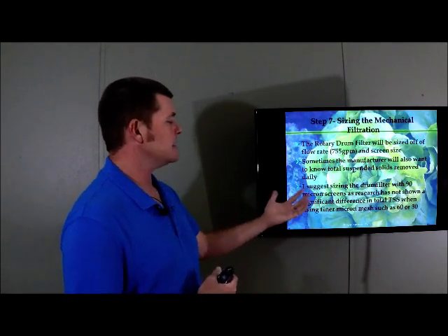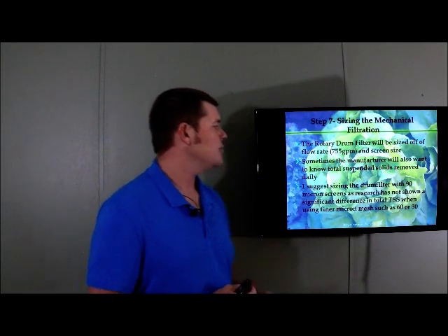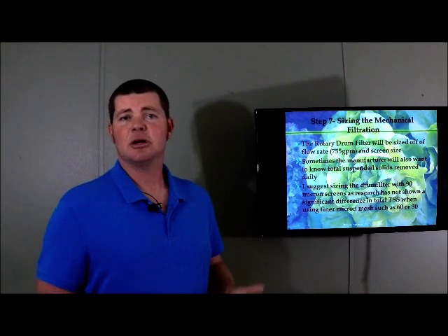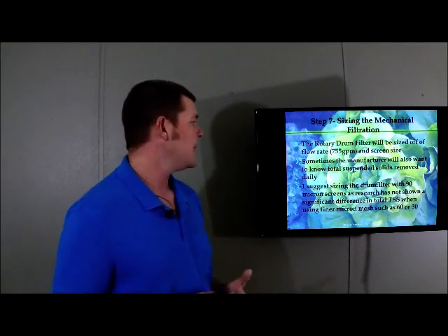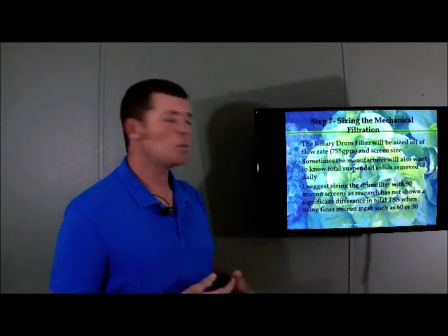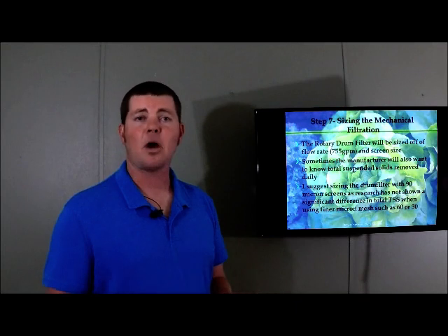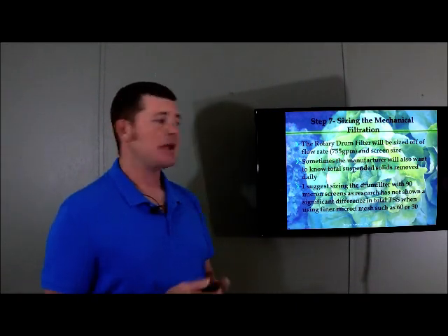And what this is basically saying is there have been tests performed, and when we use a 90 micron mesh, and we also use 60 and 30 finer meshes, we actually don't see much of a difference in the total suspended solids in that water column. And using a finer mesh will waste a lot more water. It's going to clog the screen more often, and you're going to have backwash cycles happening more frequently.